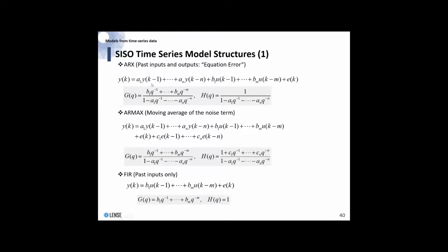In terms of transfer function, it looks like this, right? So this is the trend model. This is the causal model, the deterministic model. And our ARMAX model, with this extra input, looks exactly like this, except that now you have a moving average of this noise input, E. So that's an ARMAX model.